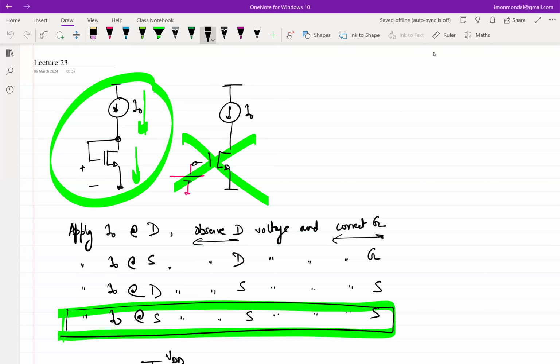So essentially, either you should have one particular voltage source which biases VGS, or a current source, right, which tells the transistor to auto-adjust its VGS with respect to whatever is needed to feed in the current. So in that vein, we didn't see all the architectures, but at least we can appreciate that the current source can be connected either at the drain or at the source, which means that we can either observe the voltage at the drain or the voltage at the source.